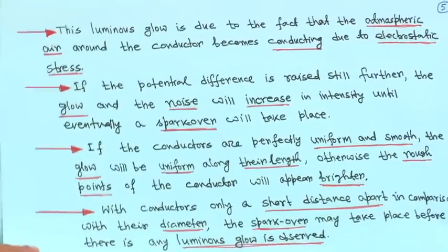At night time it will be visible. In daytime it is also happening, but in daytime you cannot make it out all the time, though some chattering noise will be there. From that noise you can make out that this is due to the corona only. You will find some kind of noise for a 220 kV line or above, right. And if you hear that hissing noise, then you can find, yes, corona is happening. This is a common phenomenon for a transmission system.